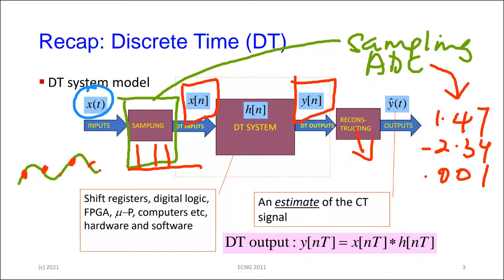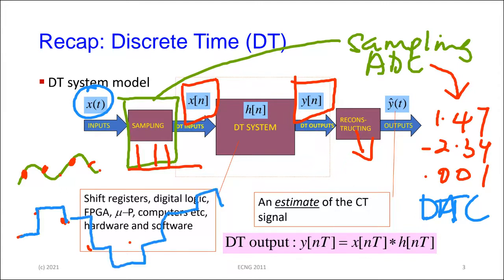And how they are reconstructed, a little bit about that: you have the numbers coming back now, and the digital to analog conversion, the DAC, which was also spoken about. Well, look at this. It will hold this value, then hold this value, then hold that value, then hold that. So you get this kind of signal coming in, right? Which is an approximation of what the original continuous time signal was. And if these steps are small enough, you get a fairly good, reconstructed real world approximation of what the continuous time signal looked like.